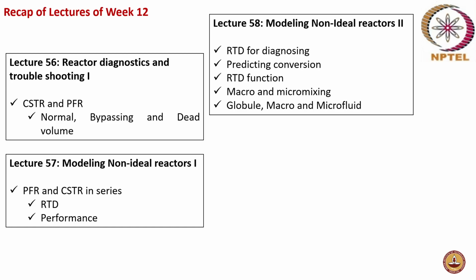Different models available, like the zero adjustable parameter model having two subdivisions of segregated and maximum mixedness model, were all discussed. And the limitations of the RTD function: we have information on how much time the material spends inside the reactor. However, there is no information about mixing or exchange between the molecules that controls the reactor behavior, except for the first order reaction, was discussed.